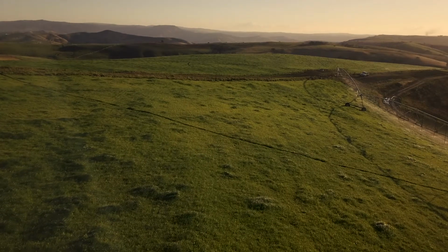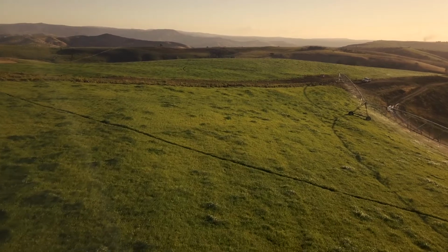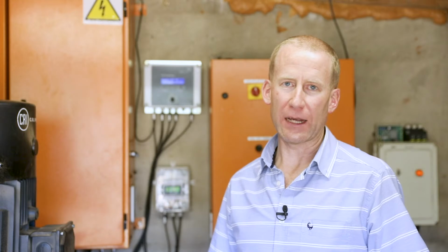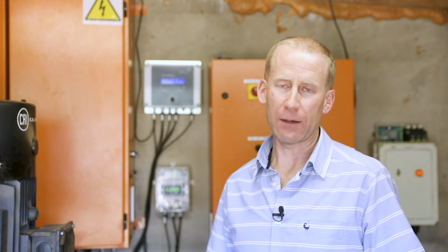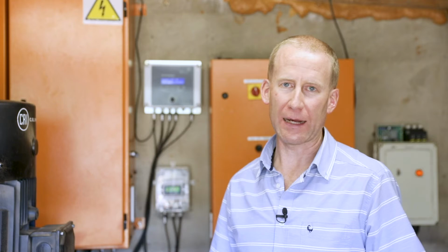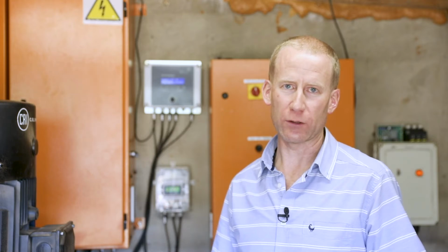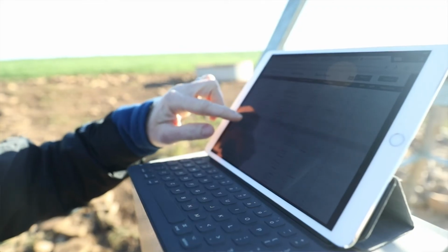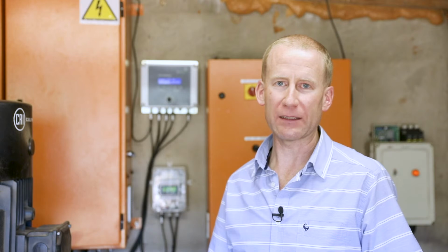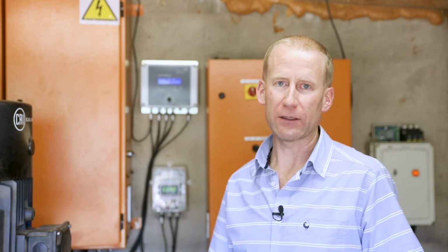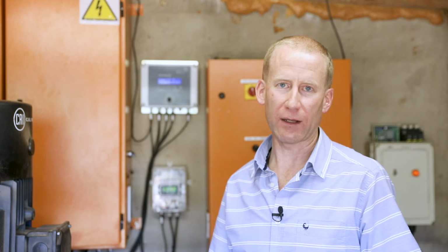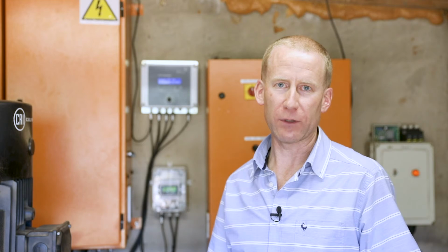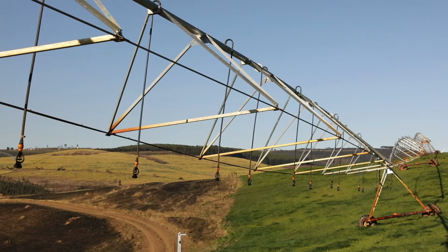The energy saving is highly dependent on the change in elevation from the pump to the pivot center, the variation in pivot elevation, and the excessive pumping pressure. We typically expect a direct energy saving of 25%. In some cases, we've achieved energy savings as high as 40% from direct pressure control. In addition, when we analyze the data that the system is monitoring, we can then optimize the overall pumping system. This includes changing the pump and motor as well as pipeline. When we optimize the entire system, we achieve savings between 50 and 75%.